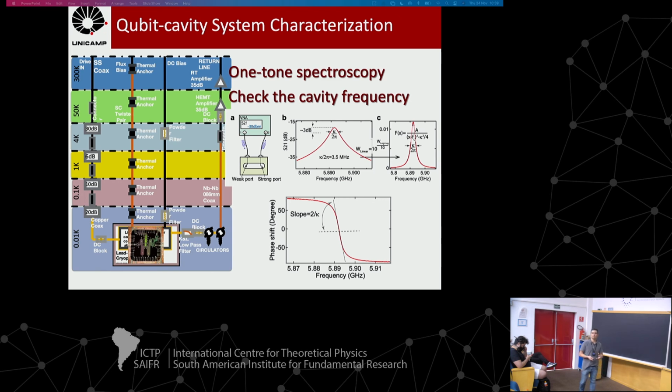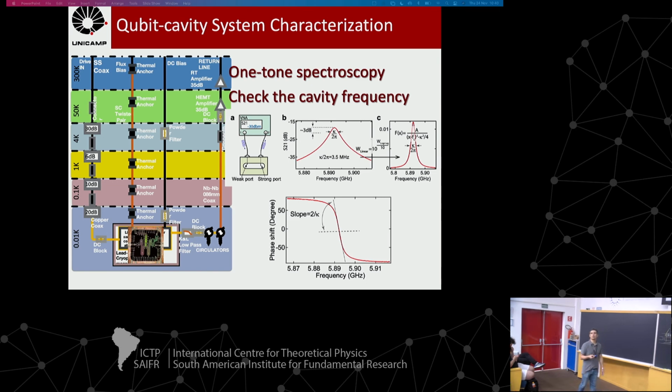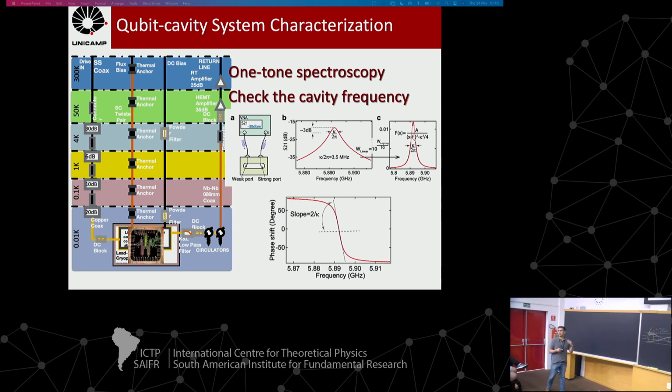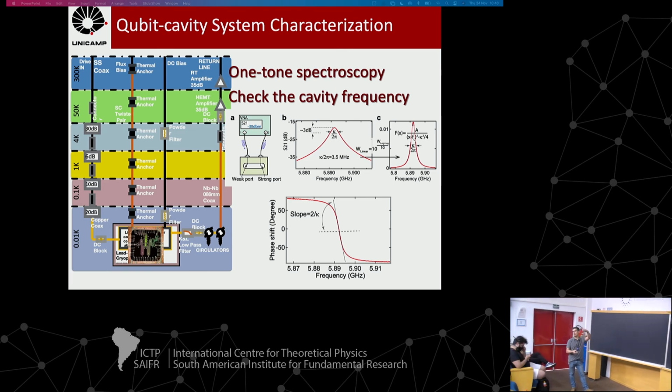Then I start to attenuate both parts, the signal plus the noise, at each one of these stages to thermalize the signal with that temperature and to reduce the signal that I created really large in the beginning, to send this signal to my sample. So I can probe now, for example, the cavity, and I can just send the signal through the same cable and excite the qubit.